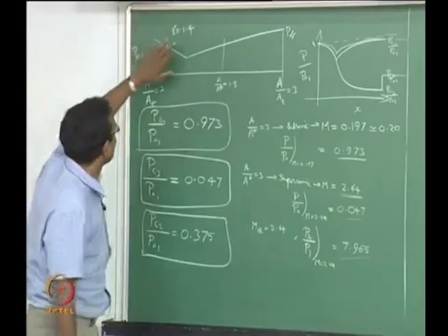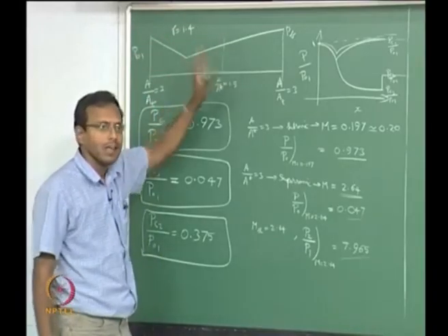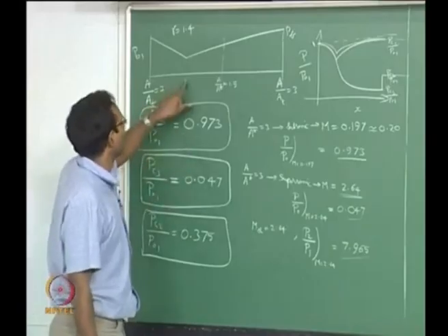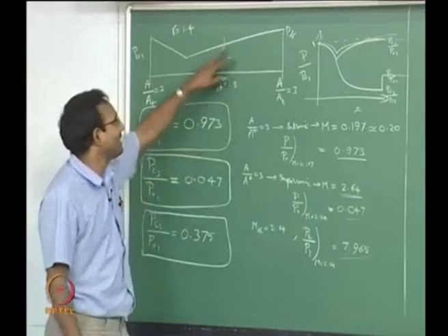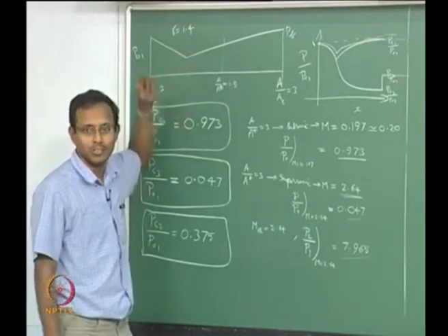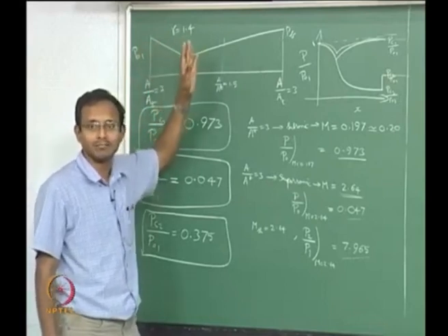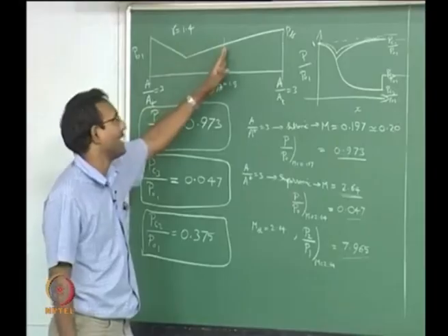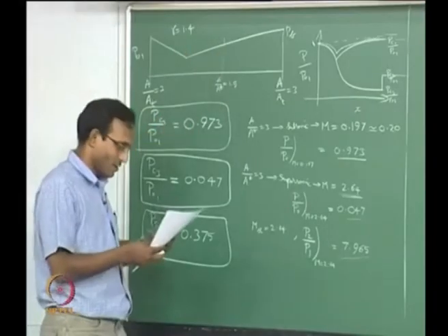Okay, now we will say that we want to find the location of the shock. Okay, I am not interested in finding the exact x location or the axial location. All I care about is the area at which the shock is standing. Once I know the area, I can just go and look at the geometry of my nozzle and tell where that area occurs in my duct. So we will worry about area at the shock location, that is all. Okay, we want to find that.